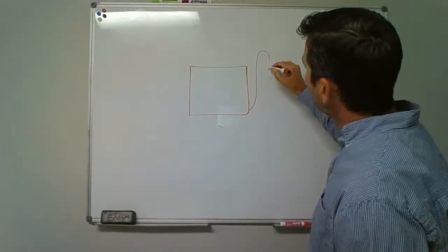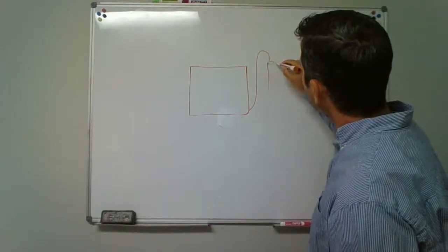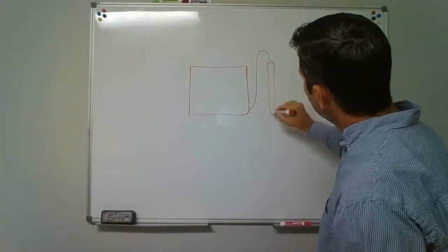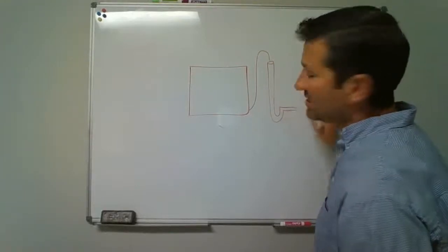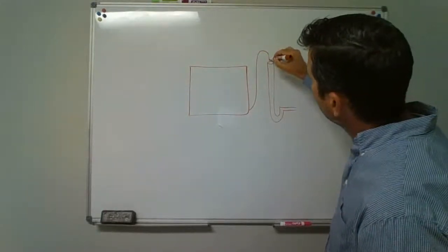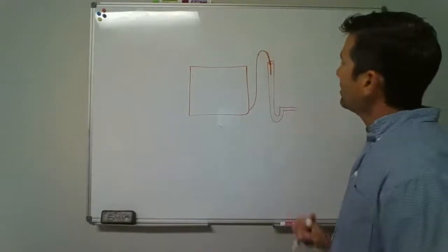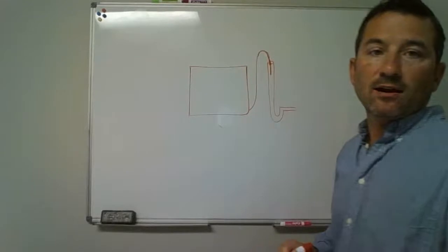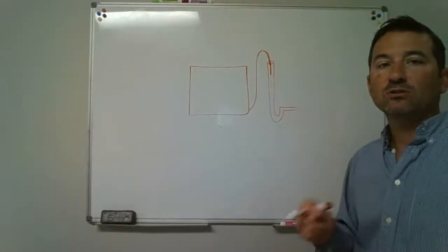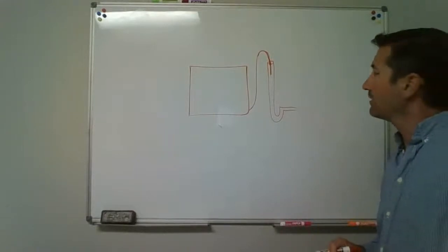So back in the wall, more than likely there's a box behind there, something that is hidden in the wall, but it's basically the opening of a piece of pipe that goes down into a trap, and that goes off and is tied directly to the rest of the system, glued together joints and everything. But that hose is just hanging down into there. So hanging over in there, it's not directly connected. It's not a solid joint glued together or some type of mechanical band clamping that on there.